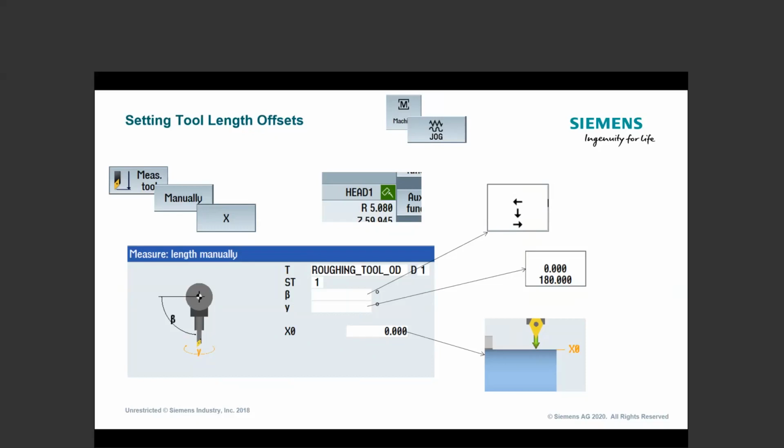I want to turn a little bit on the diameter and check it. I can swing the B down, flick the spindle over, take a cut, do my set X, type in my diameter, and then it's going to know that position. So if I swing it back up and go back to 0, it's going to track all that.